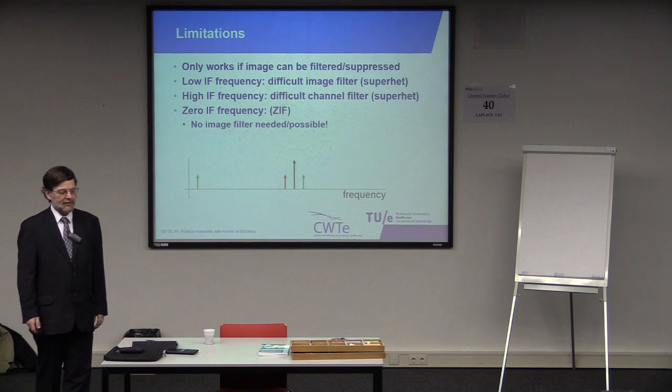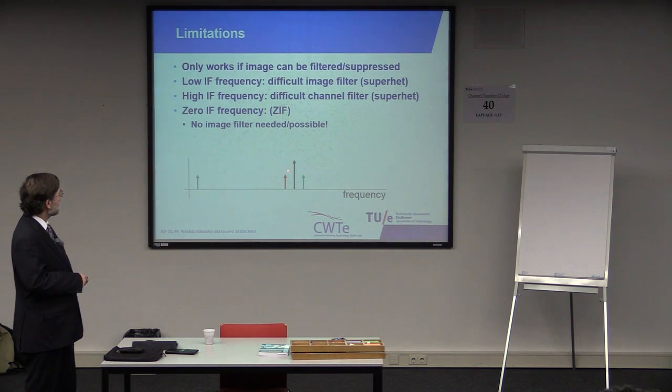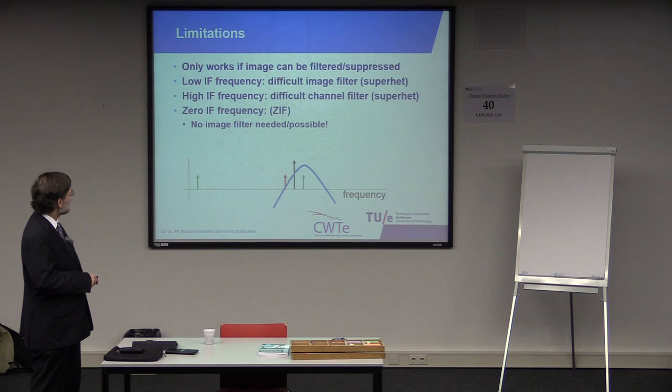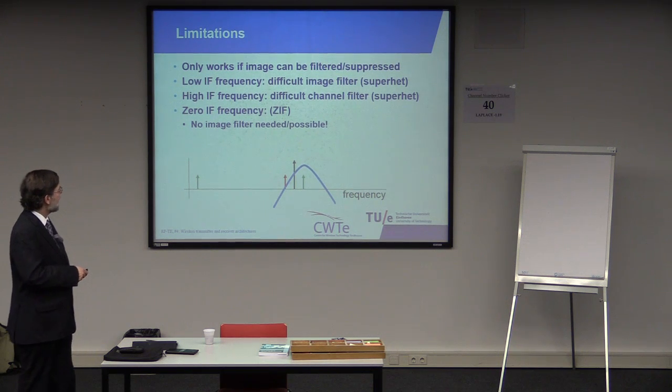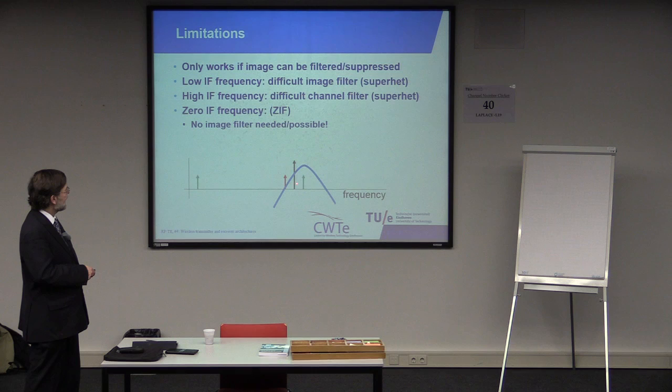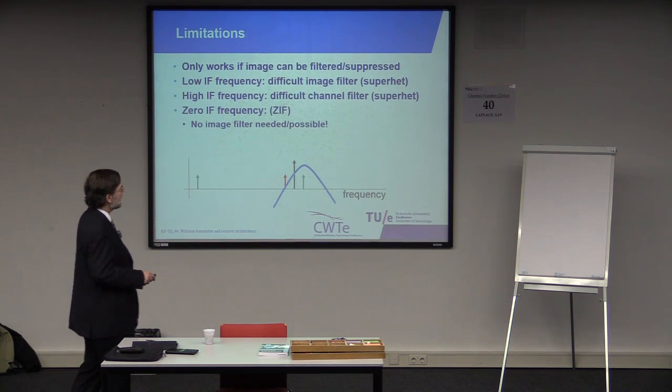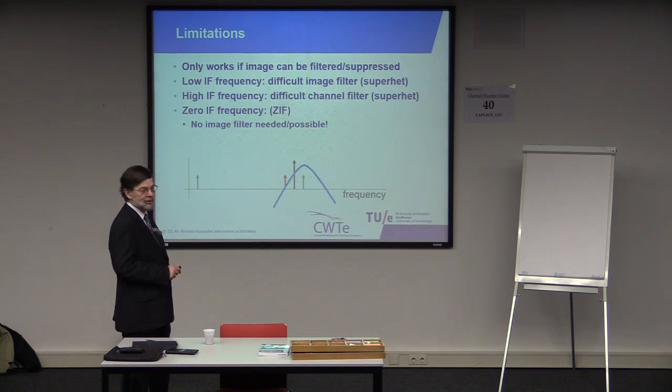So you have this, and we can look at that in the diagram. We have this system where we have a wanted signal, and we have an LO signal that we want to use to shift this green signal to this low frequency. And the problem that we have is if we do that, then this green signal and this black signal, if they multiply together, they will also give a component at the sum of these frequencies.